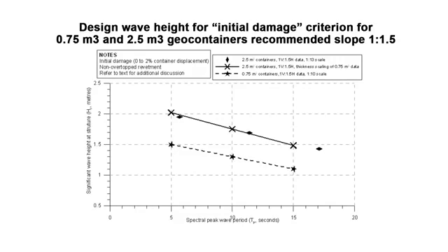So 5-second waves are what you might see in a reasonably sheltered waterway, say on the shores of Moreton Bay, where you've got a 5-kilometre fetch, 5 kilometres of water before you reach land on the other side. So that's the sort of waves you'll get inside Moreton Bay, 5-second waves. A big long-distance swell, say generated down in the Southern Ocean, typically is up around 15 seconds, can be 20 in some circumstances. So most of the open coast of southeast Queensland and New South Wales is generally in the 10 to 15 second range for wave period, but an enclosed water body more like 5.